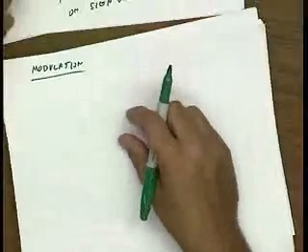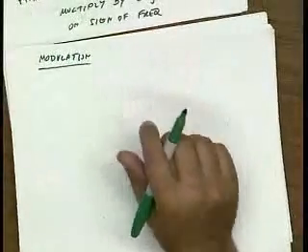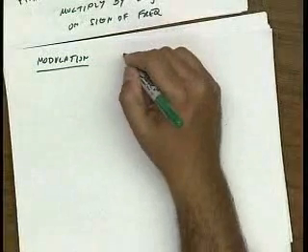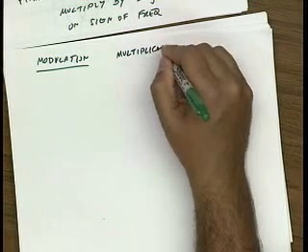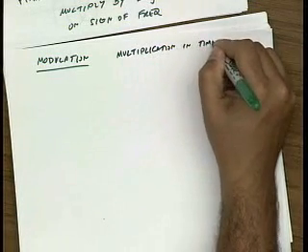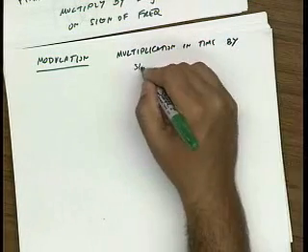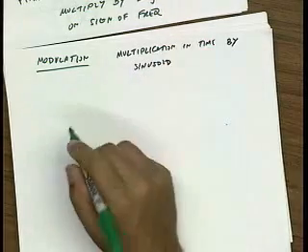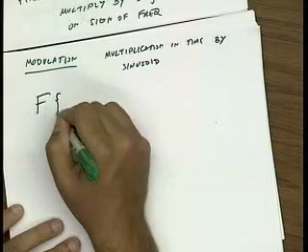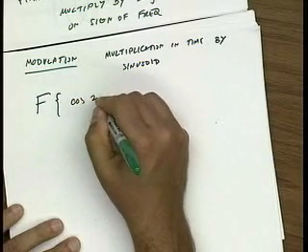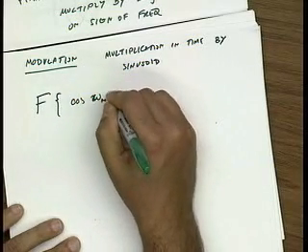Okay. So modulation, in fact, if we look at frequency multiplication, this is multiplication in time by a sinusoid. That's what we defined as a perfect mixer operation. Let me take the Fourier transform of cosine omega m t.